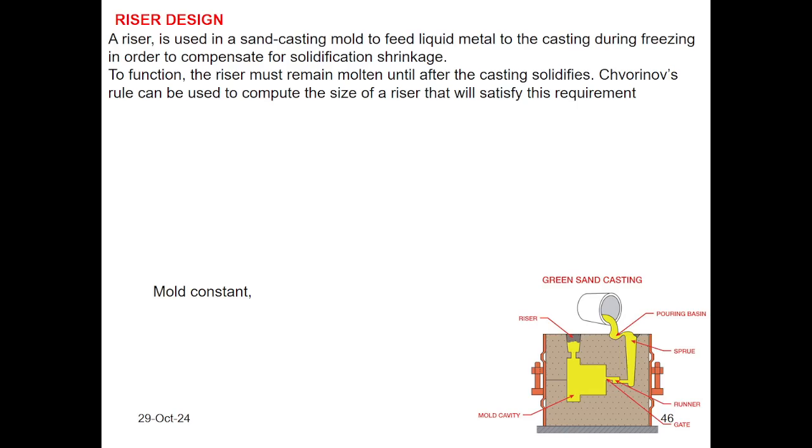Okay, you know the function of a riser. A riser mainly is used as a reservoir. In sand casting, it is to feed liquid metal into the casting cavity during freezing, during solidification, to compensate for solidification shrinkage.